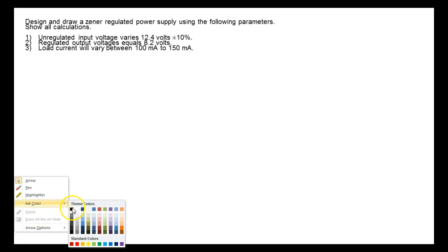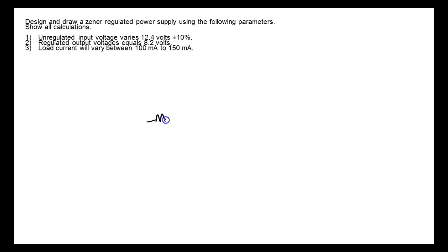we're going to choose a size for RS, and then we're going to choose a Zener, and it's a positive supply. I can't remember what it is over here. And then we're going to come up here, and just to keep from burning up our pot, we're going to use a 100 ohm resistor, and then we're going to put a potentiometer wired to act like a rheostat. And we're going to measure load current.